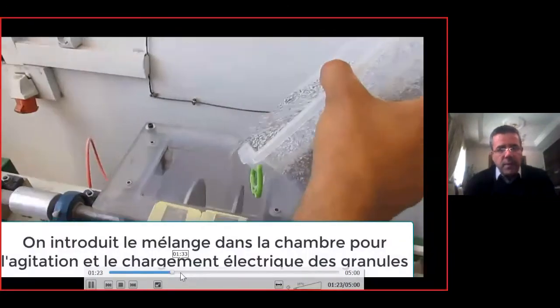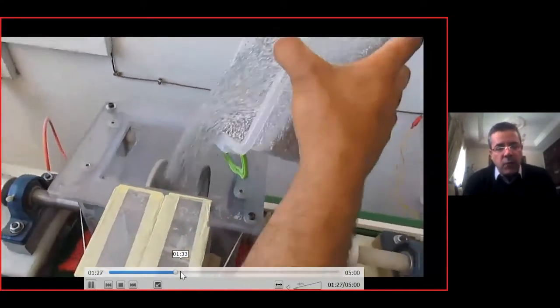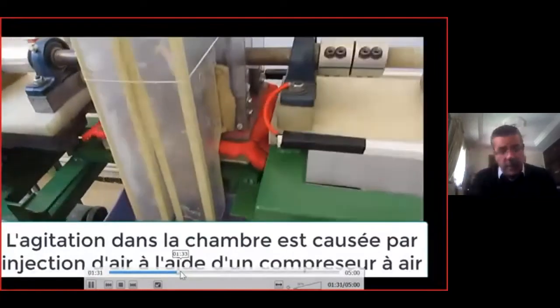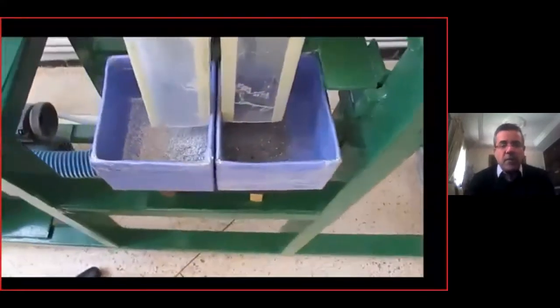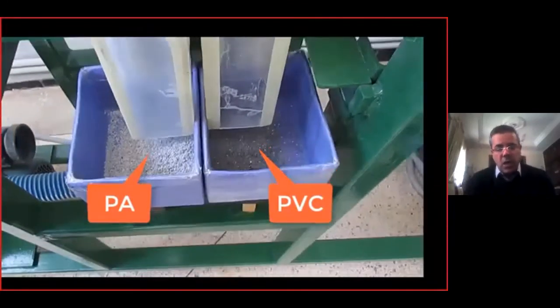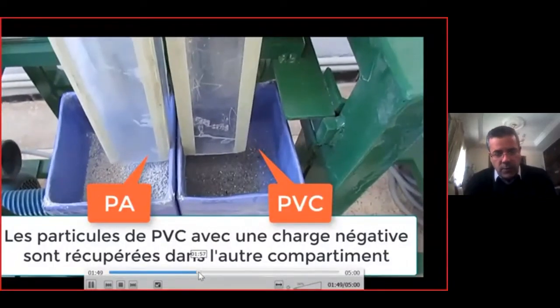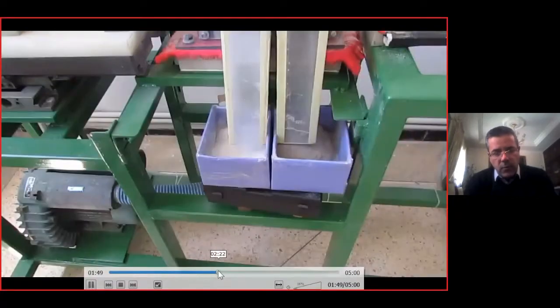Each disc is connected to a high voltage power supply, and there is an ejection of air below. So after we have separation, because each type of plastic will get one positive charge and the other negative charge, they are separated. If you want more details, I will let you have my others.